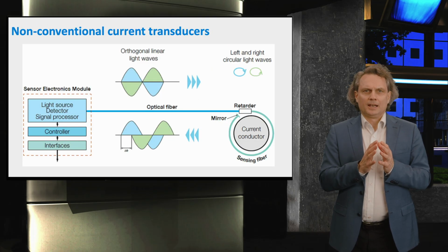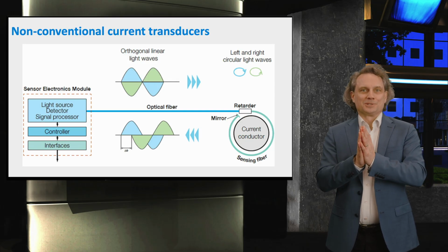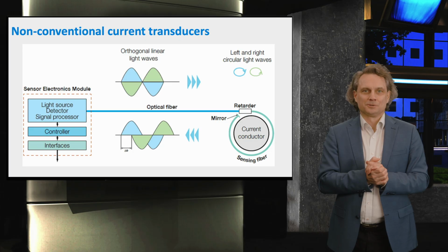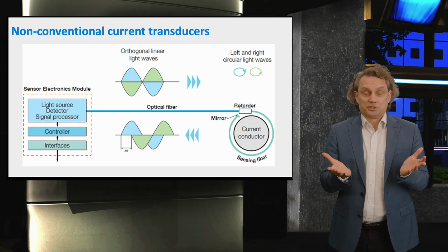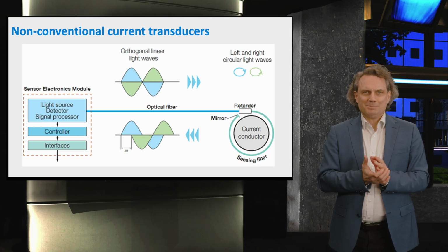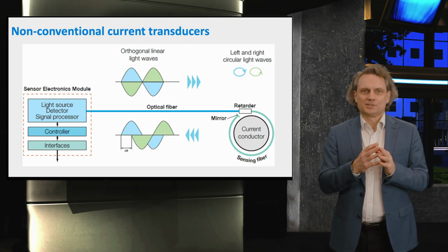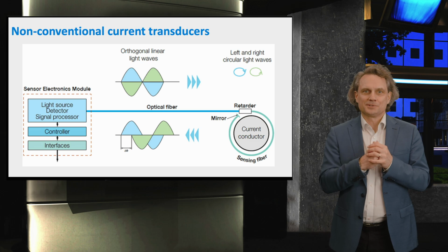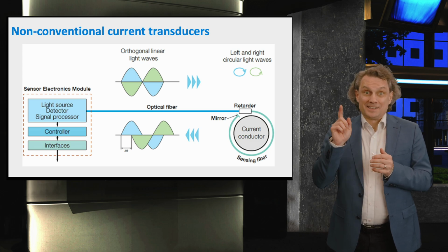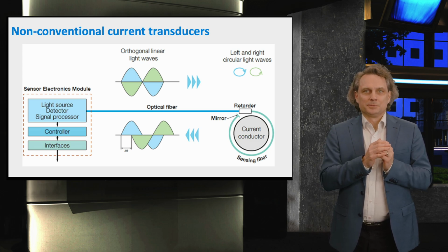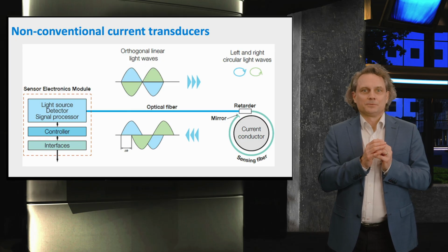Another digital element that you might find in a digital substation are non-conventional current transducers, also referred to as non-conventional CTs. They are sensors to measure current, but unlike traditional ones that are basically small transformers, measurement transformers, they use a magneto-optical material and the Faraday effect with polarized light in an optical fiber.